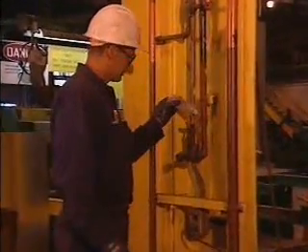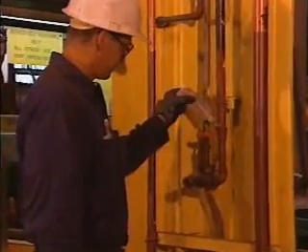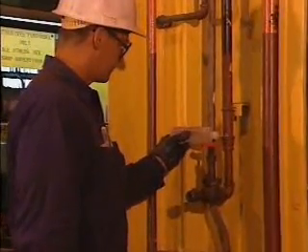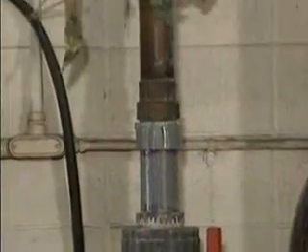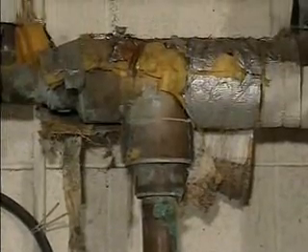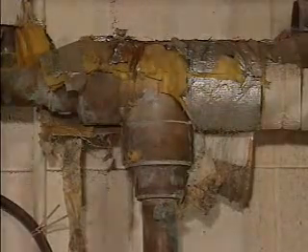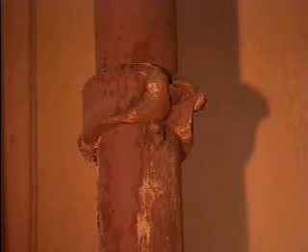Because a small leak or blockage in just one pipe can impact the operation of the whole system, routine inspections are an important part of maintaining any piping system. Inspections involve examining pipes and pipe fittings for wear and damage. One of the most common types of damage to pipes is corrosion. Corrosion is the dissolving or wearing away of metal. Corrosion can be either external or internal.